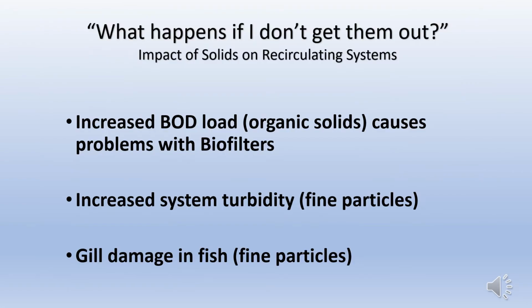One of the questions that we need to ask ourselves right away is, what happens if our filter system doesn't really work, or it doesn't work well enough to get all the solids out? What happens? Well, here are 3 points, and below I listed some words of wisdom from Tom Lasordo. He's one of the people who designed some of the more advanced filtration systems that we use at the lab, and I'm going to let you go ahead and read that one yourself. But the bottom line is, when you look at the increase in the biological oxygen demand caused by the presence of too much sludge or solids, that can be a real problem for your fish in your system, and even your bacteria in your biofilter.